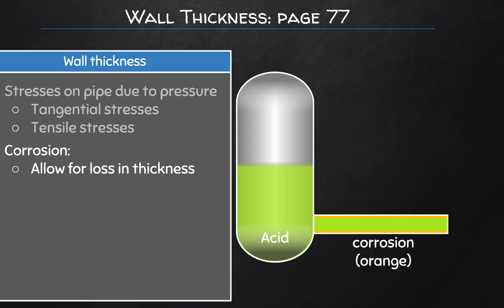Any contaminants in small quantities, and just don't assume that corrosion won't be an issue. Water can be quite dirty. It's only very special water that is cleaned very well that might not cause such issues. Usually when you have a very concentrated acid like sulfuric acid, it won't be as corrosive as a dilute acid towards stainless steel, for instance.